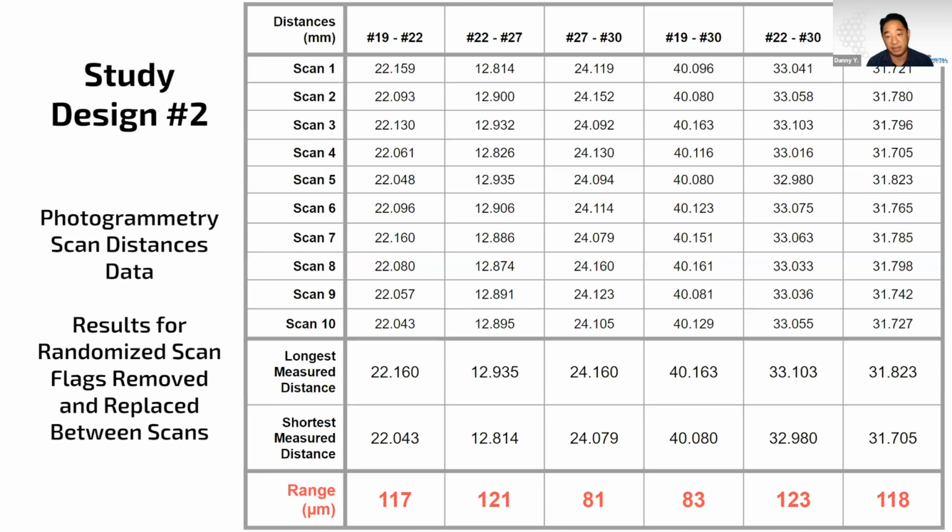You could see the effect that the screw hole tolerance has on the accuracy and the precision of this device being repeated over and over again. Now the story is about 40 to 60 microns of accuracy. That makes sense in terms of the distances from each other, because we're measuring the distances between two implants. If one is moving away and one is moving closer, and also in the opposite direction from these two points, we could see that 50 micron screw tolerance basically right there in this data.